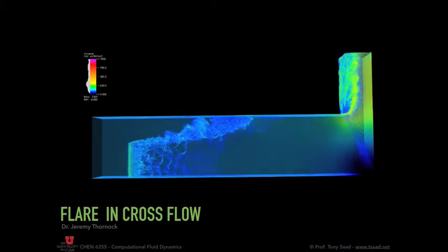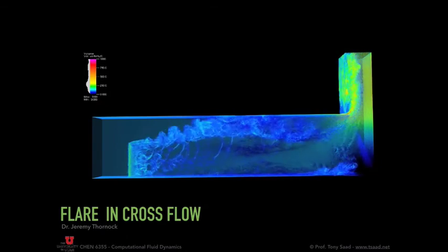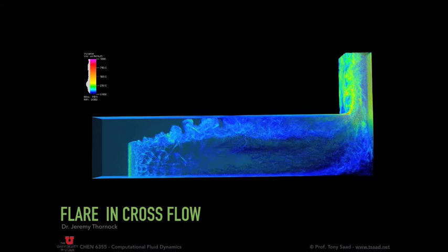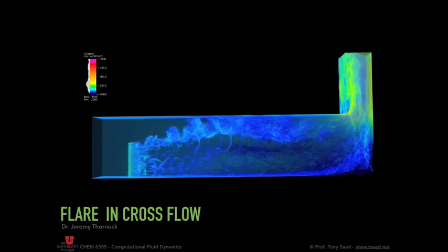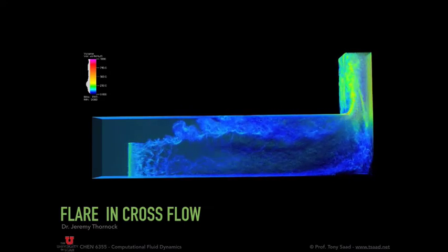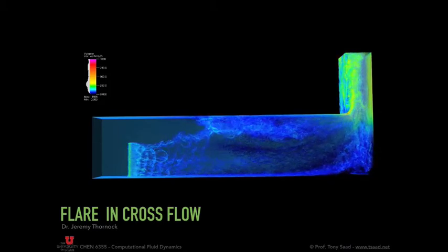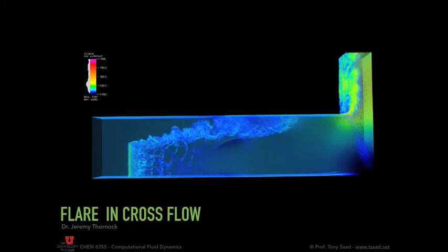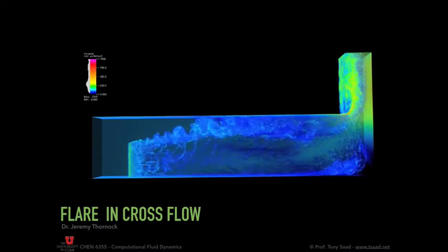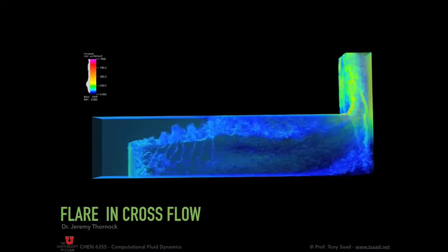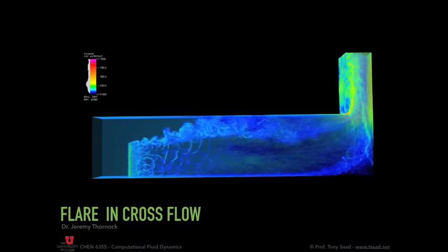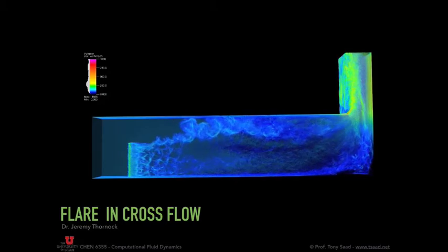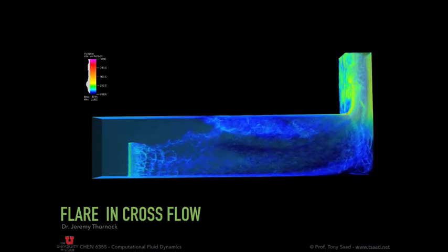So if you have flow that has equal velocity across and that is moving forward, there's no rotation because all the fluid particles are moving at the same speed. They're parallel to each other. There's no rotation, there's no spin, like you said. But when different fluid particles are moving at different speeds, they're going to interact with each other and they're going to spin. They're going to start rotating, and they create this thing called vorticity. Vorticity is very important in mixing.